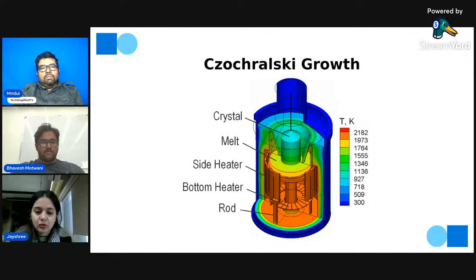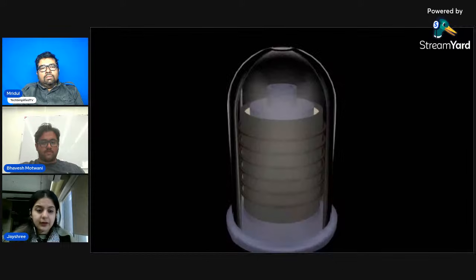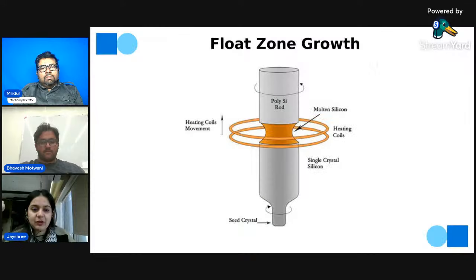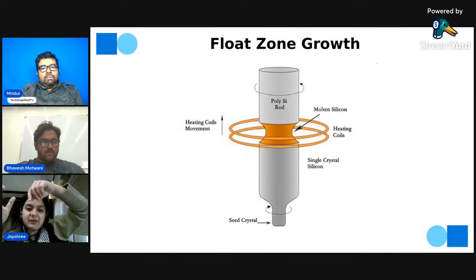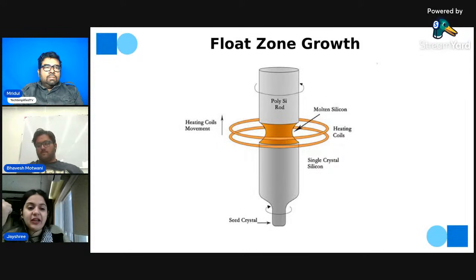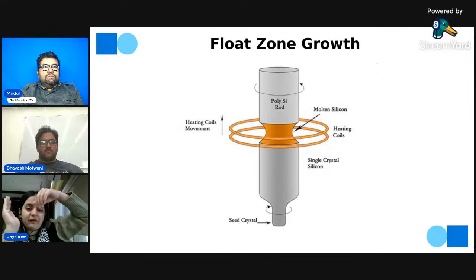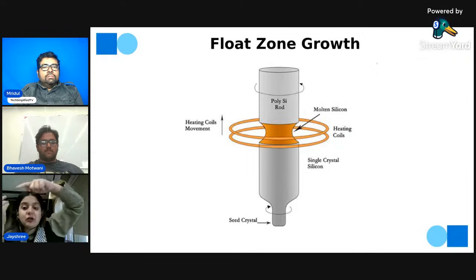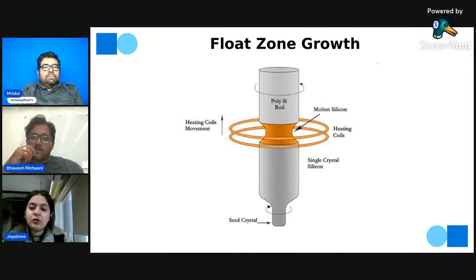Okay, and in this crucible also, there must be minimum vibration and great precision, so that the crystal growth process and the crystal rotation process are very smooth and soft. That way we get the ingot without damage, and without certain parts being left behind in the chamber itself. We need to make sure of that, it's very important.